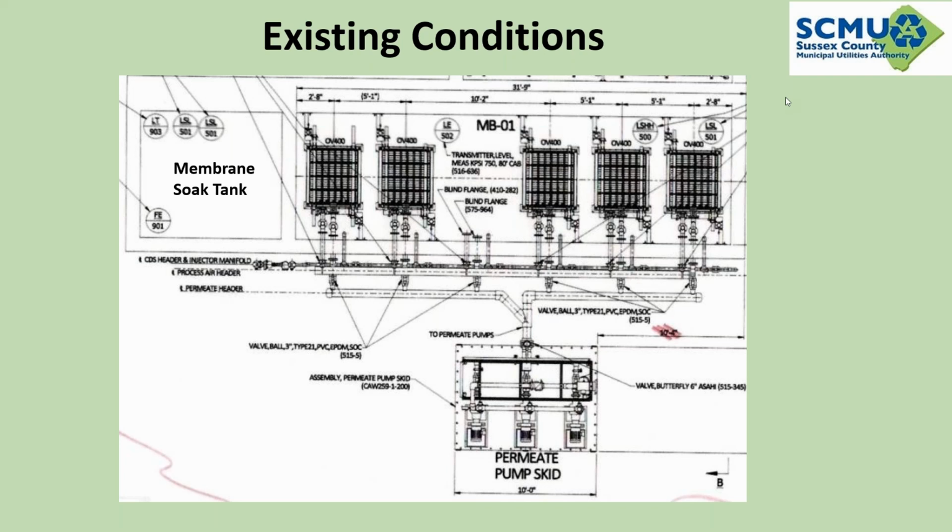One of the other things to note, which obviously you can't tell in plan view here, is that all the connections are actually under the water level. This was a huge issue in terms of performing any type of maintenance on this equipment. In order to do any maintenance, you at a minimum needed to lower the water level such that you could unhook the flanges, which had its own issues with how tight those were. And there were 4 pick points for these units, so again, you had to lower that water level to even access those pick points.